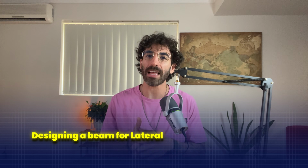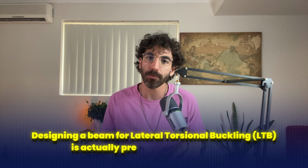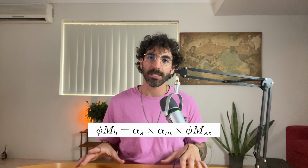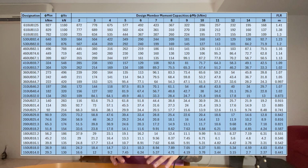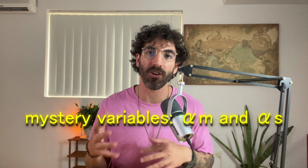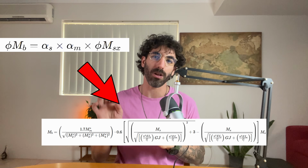Designing a beam for lateral torsional buckling is actually pretty simple. In theory, if you look at the code, you will find an equation that looks something like this: alpha S times alpha M times the section capacity. Since we already know the section capacity phi Msx from the tables, all we need now are the two mystery variables, alpha M and alpha S. Seems easy, right? Well, not really, because that nice clean formula actually looks more like this.